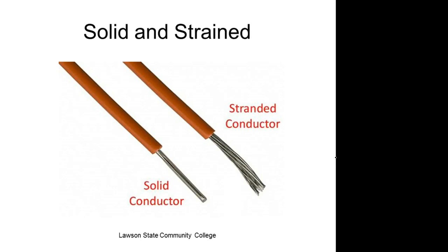And we can see this on our trainers, especially our old trainers. There are little wires sticking out that we have to dig out because people didn't strip the wires properly. So on a solid strand wire, if you accidentally put a little scribe in it, that wire's going to break over time. Because it's solid, you scribe it just like glass, right?